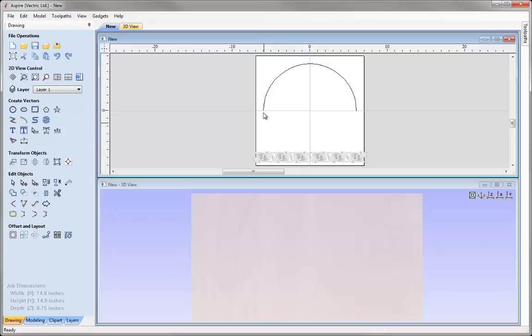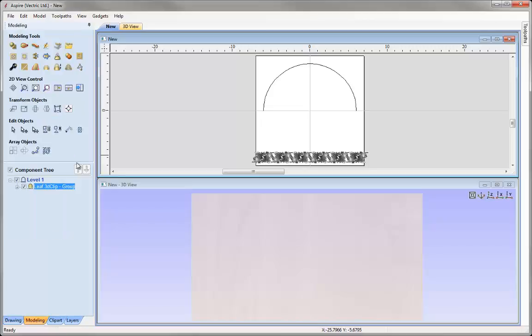Now there are two ways we can extrude our components along here. We can take a single set of components like this and extrude them along with multiple components and an overlap, or we could group everything together as a single component if I knew I wanted exactly this number, and then we could extrude that along there. So let's show you that method first quickly. We'll take these, let's group them together. So we'll click on the icon there to group them, and we've got a single component, or at least the software will consider it a single component.